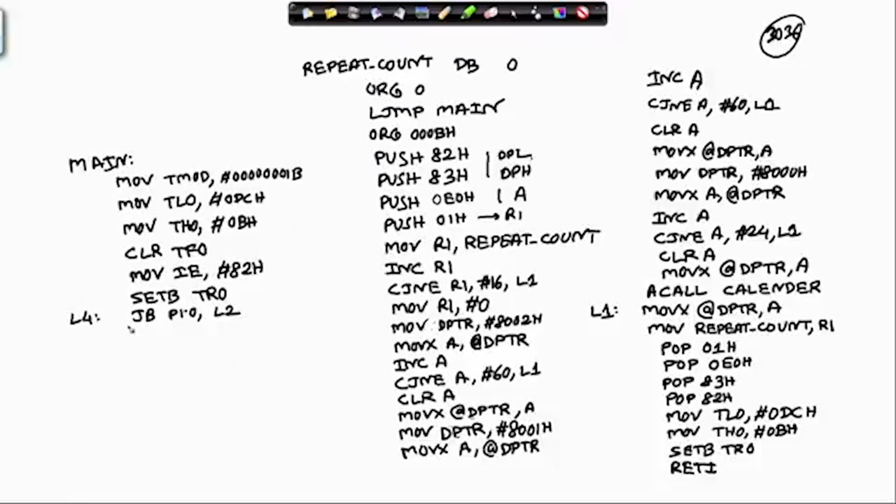If the mode button is not pressed, then this bit is 0. So, we should display the date part. In that case the DPTR register should be loaded with the value 8000, and then I can just jump over to L3.